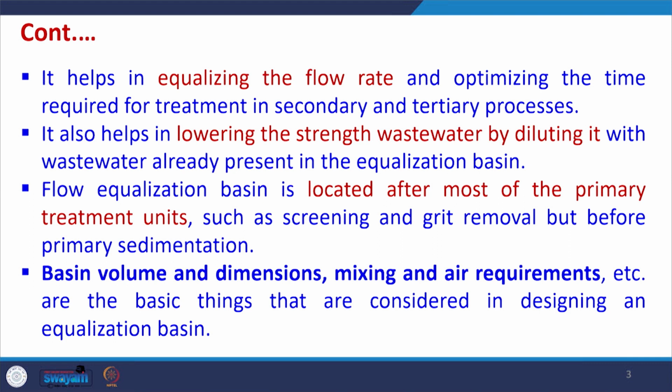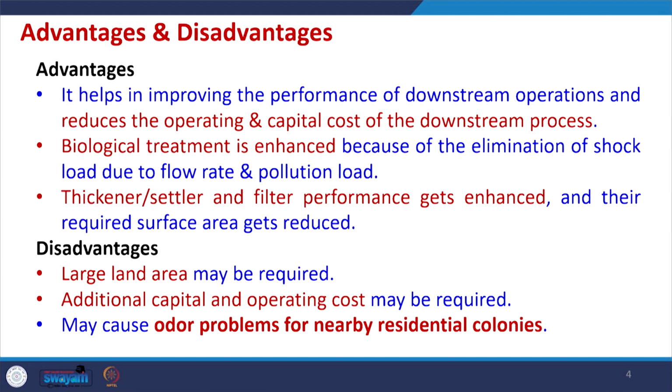Basin volume and dimension, the mixing and air requirement etc., are the basic things that are considered in designing an equalization basin. Now, there are certain advantages and disadvantages of using the flow equalization basin. The advantage is that it helps in improving the performance of downstream operations and reduces the operating and capital cost of the downstream processes because the flow is being equalized.